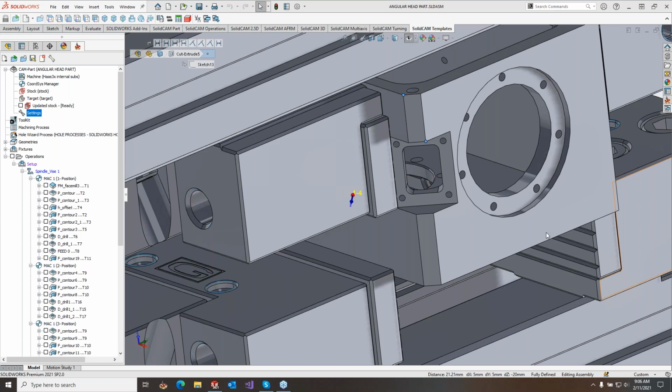Even in SolidWorks, I think for anybody that's ever tried modeling a thread in SolidWorks, draw a helix, draw a thread profile, revolve or cut along a long curve, it really increases the memory and really decreases the speed. So at the moment, I do think we show threads. I think there has been talk amongst us about not showing the threads, or having an option to show fake threads to speed it up, because when we do turning threads, it really slows it down.